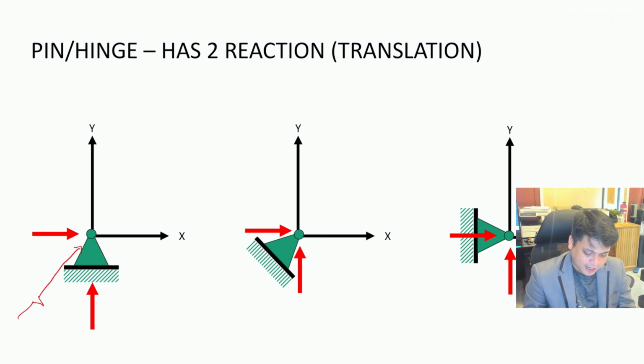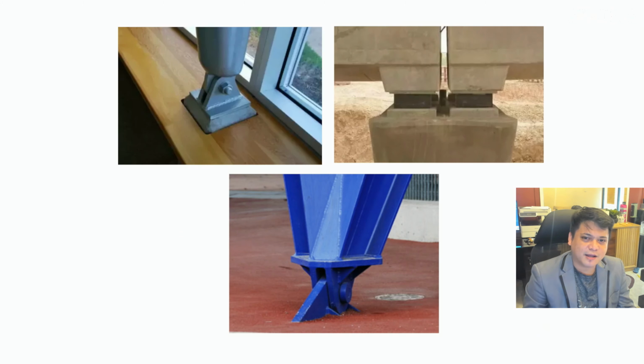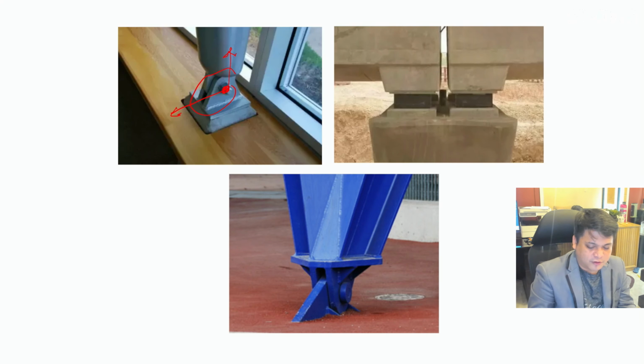So, what are some real-life examples of our hinge supports? Yeah, so those are the hinge supports. It prevents us from translating. Like in the first picture, this joint cannot move here, and it cannot move over there, but it can rotate. It allows a rotation in this kind. Same thing for this one. So again, its reactions are 1 and then 2. You always have two reactions.